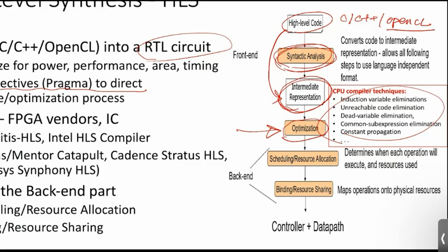After that, you do the high-level synthesis specific optimization. Here, in particular, I talk about scheduling and resource allocation, and then binding to the final target hardware architecture or hardware components. So this part is kind of a data path compiler.